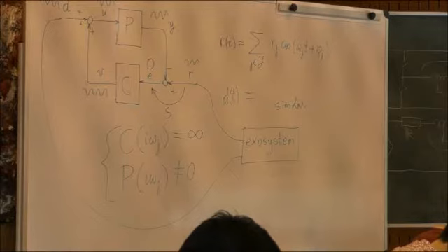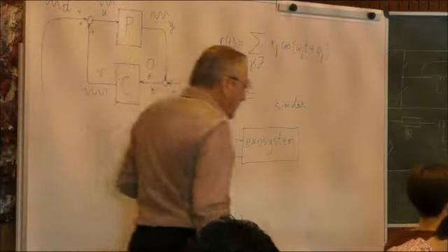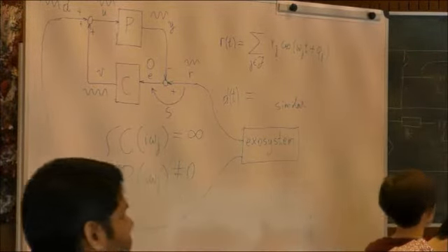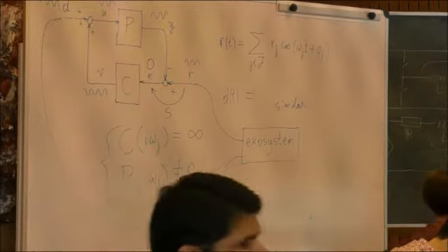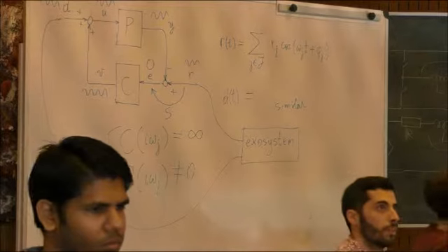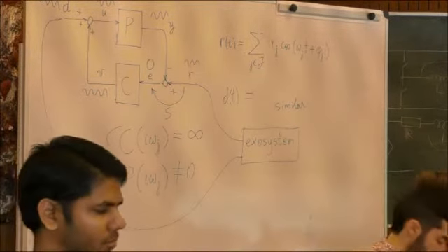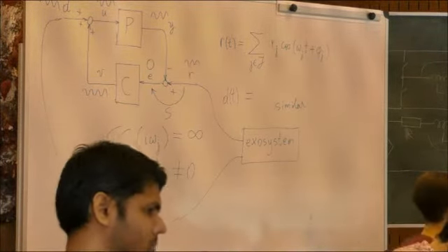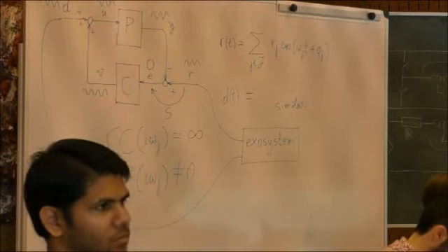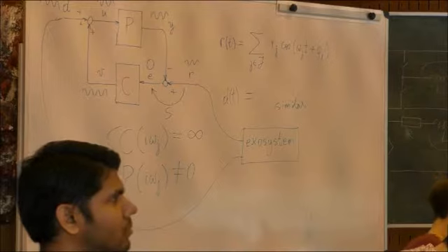So the simplest example, if we go back to the beginning of today's lecture, is a PI controller. The PI controller contains an integrator. An integrator, if you give it 0 input, what is the output of it? An integrator with 0 input, how is the output? Depends on the initial condition. Yes, so it keeps the initial condition constant. So the output is a constant.